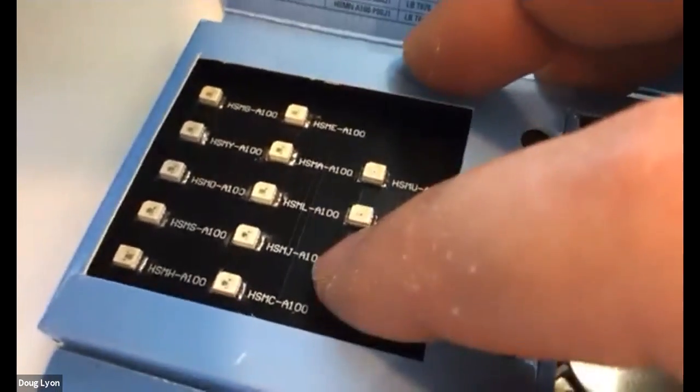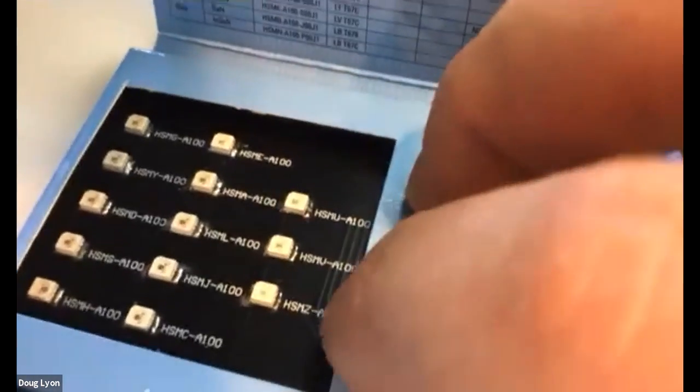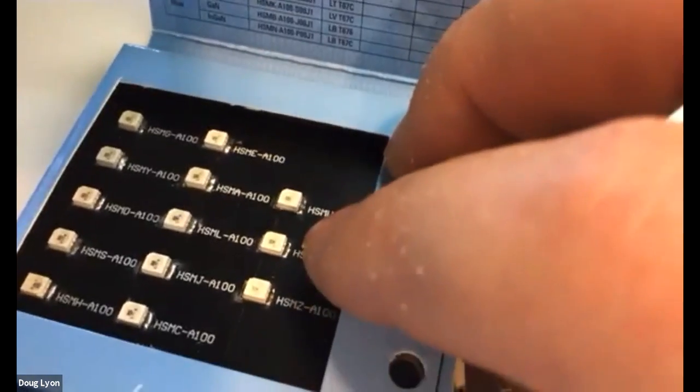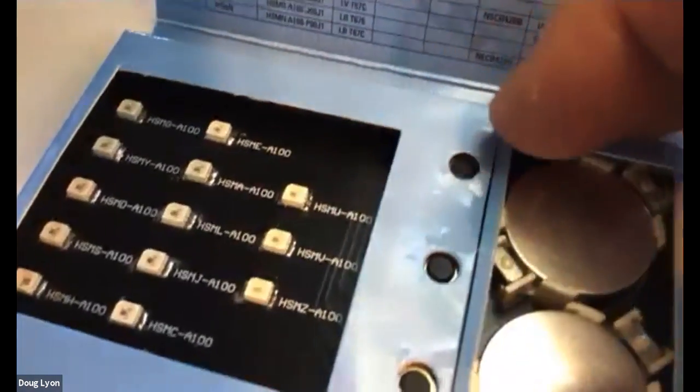Then it goes through an oven called a reflow oven, and it heats the solder so that it melts. Because there are pads that accept the solder and a wetting agent called flux, it sucks the surface mount device right onto the printed circuit board, so you don't have to solder individual leads. You basically can solder the whole board at once.